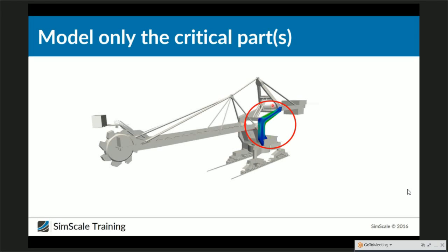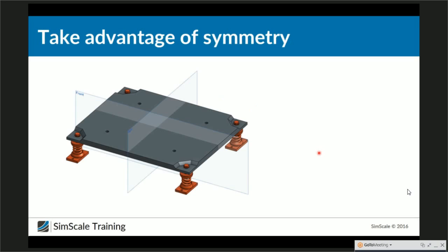We only have to define half of the contacts, half of the mesh, half of the boundary conditions. It needs to be loaded and computed, and this depends for sure also on the mesh size.